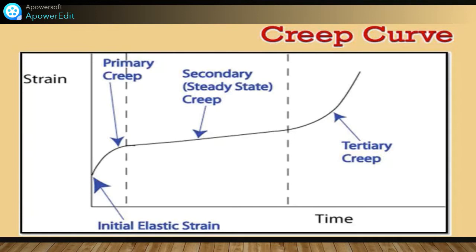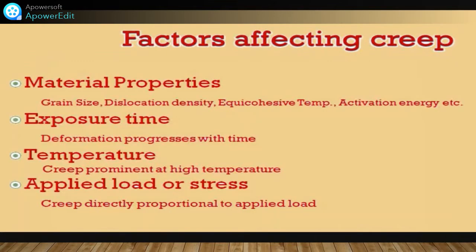This stage is most understood. The characterized creep strain rate typically refers to the constant slope in the secondary stage. Stress dependence of this rate depends on various creep analyses. In tertiary creep, which is of not much importance as far as practical applications are concerned, the strain rate exponentially increases with stress because of necking phenomena.